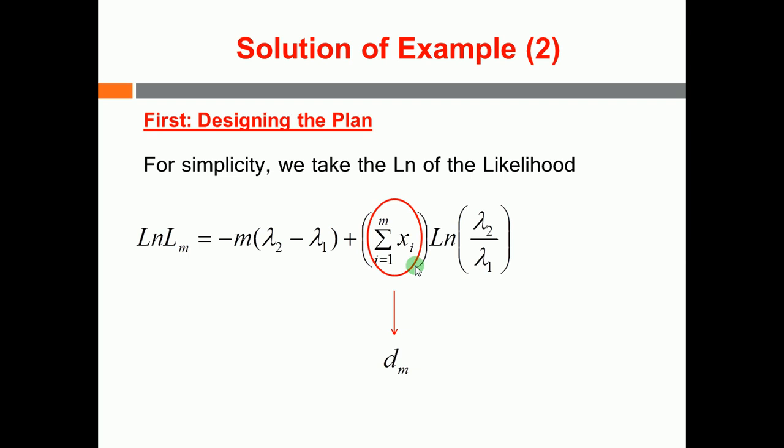Not cumulative number of defective, no, it is the cumulative number of defects per item till item number m. For example, if I investigated the first piece of cloth and I find out that I am having 4 defects, and the second piece of cloth I found out 2 defects, then in this case the DM would be 4 plus 2, that's equal to 6.